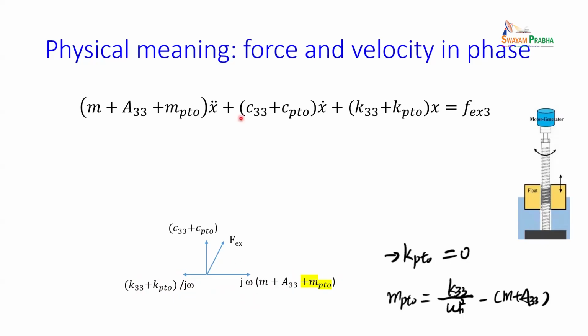So everything looks into this equation, right? You write in frequency domain, and in frequency domain here, that is single frequency, x equals capital X times e^(jωt), right? So in that way, we want to cancel this effect of stiffness and mass, so that the force direction and the velocity direction are always in phase.